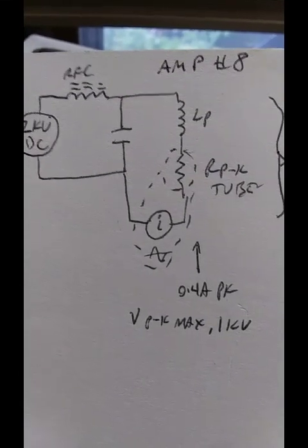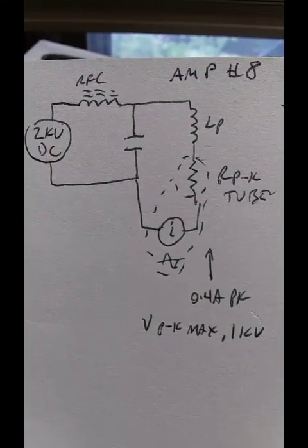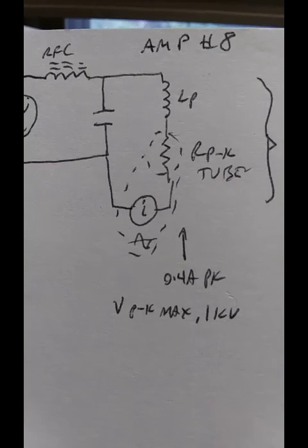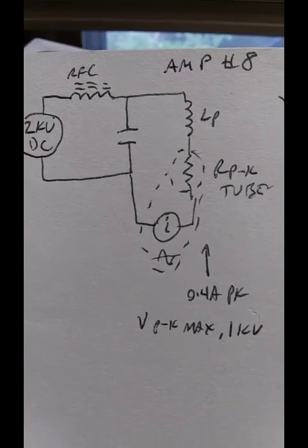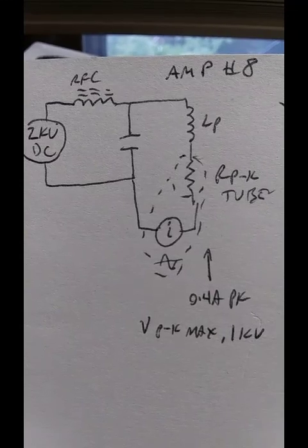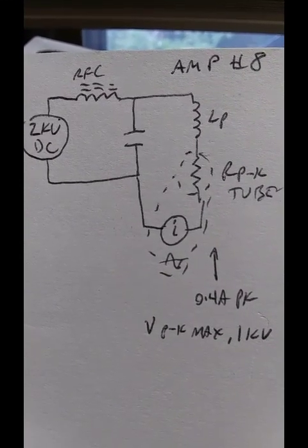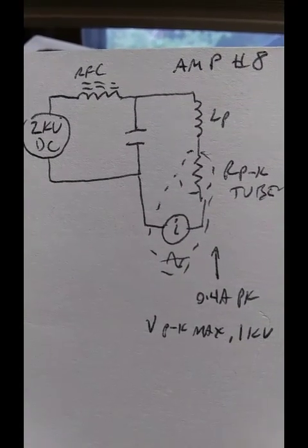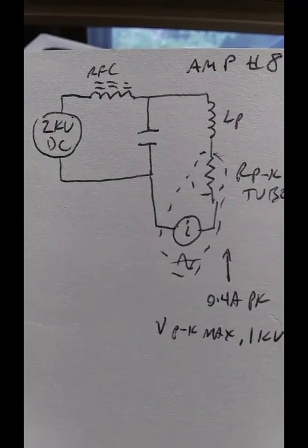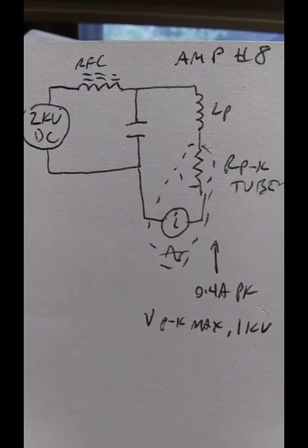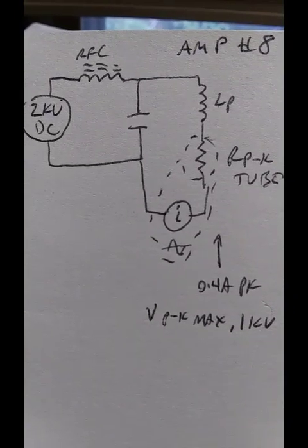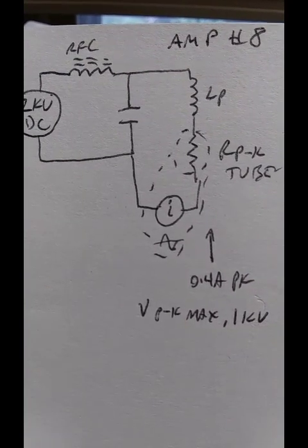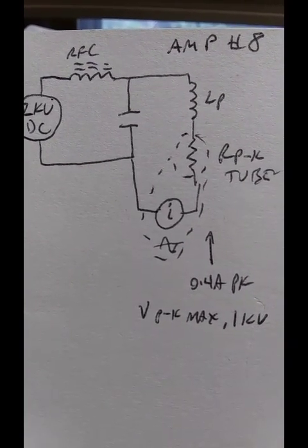That's all well and good, but we're still in deep trouble because we don't know the voltages across that inductor and the maximum voltage. The current is what's used to essentially rate a toroid coil, which is what I'm going to use. That doesn't really apply in an air core, but air core coils have a lot of losses to nearby components or shield walls, so I'm going to use toroids. The voltage also figures into the toroid core because it'll be rated with the voltage withstand, maybe 500 volts. That isn't much. So the wire insulation has to be rated and maybe the core taped, then worry about heat. So it's very important to know the maximum voltage across the inductor, and that's even trickier.